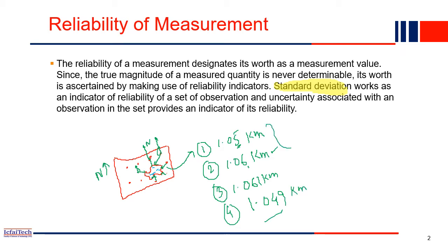We take multiple measurements for each distance, and similarly for angles also. It is not like we measure one angle once; we measure the same angle in multiple sets. You see each set will have small variations, because that's what the error introduces, right? And it is a very long distance, so there will be small errors of this type. Once we get maybe 10 or 15 measurements for the same distance, then we plot histograms.